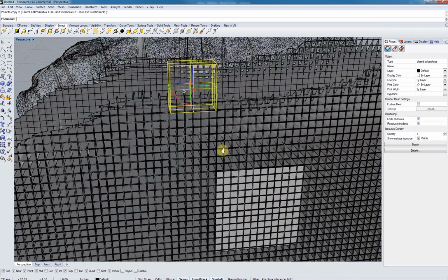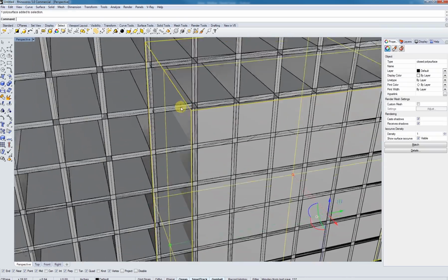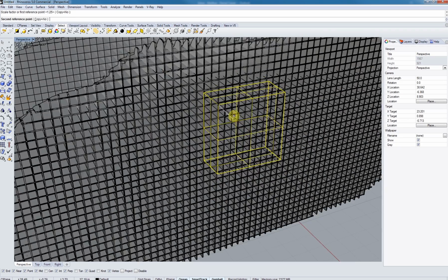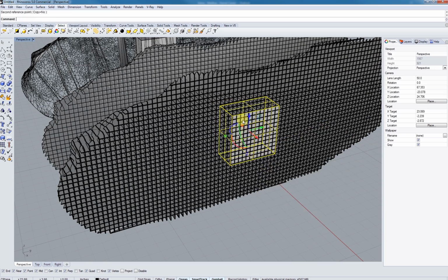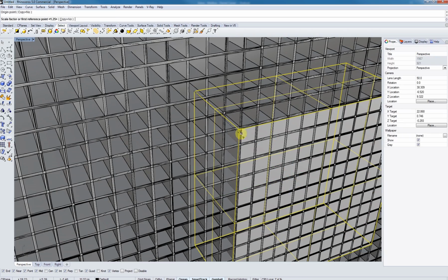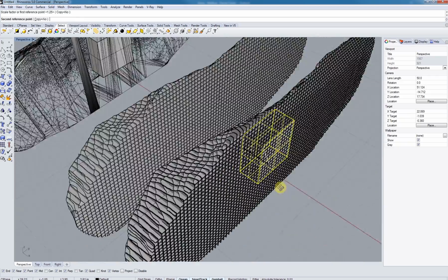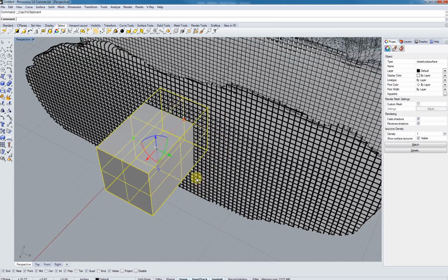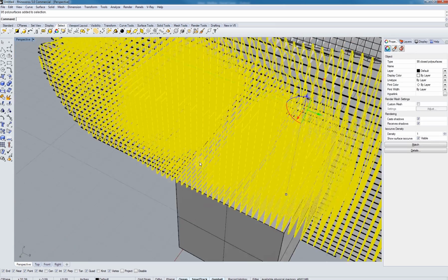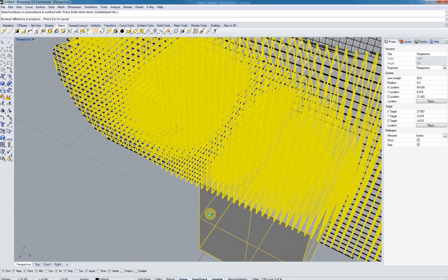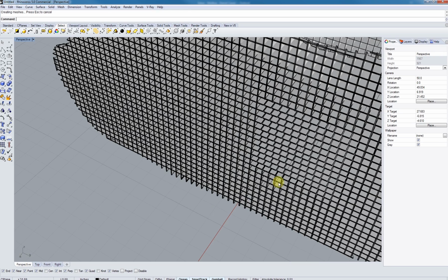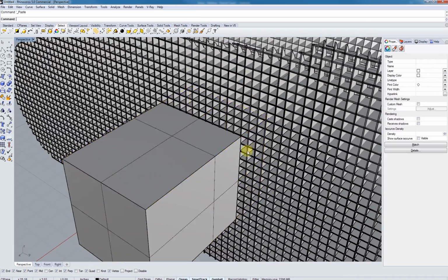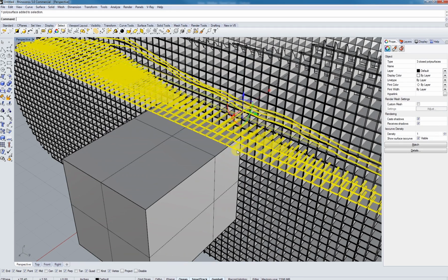Basically what you want to do is take your bounding box from your original waffle and scale it in one dimension so it's larger than your waffles. So it's sticking out similar to this. I typically just copy it because I'm only going to do one set at a time. So select one set of your waffles here, hit the box. This should be a relatively easy Boolean. And then if you had your box copied, just copy it back out. And I didn't have these guys grouped, so that's kind of unfortunate.